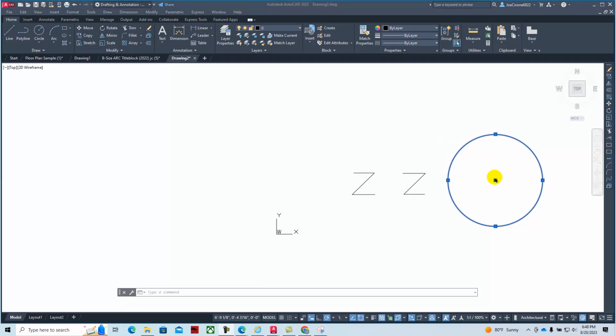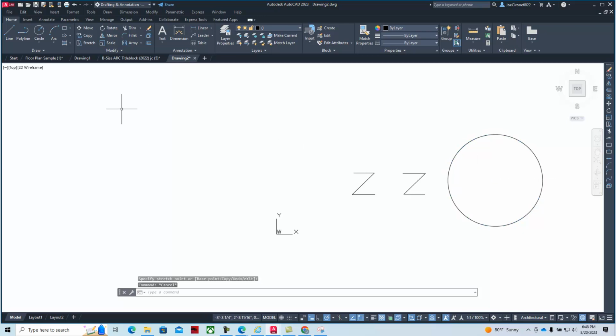And I'm checking on this, and as I look through the chapter, it's actually supposed to be 1 inch, and so this is a good example. And so 1 foot radius is 12 inches versus 1 inch. If I wanted to make a 1-inch circle, I can go here, center radius, and I can click here for the center point, and I can say 1, and then inch mark is the quotes.